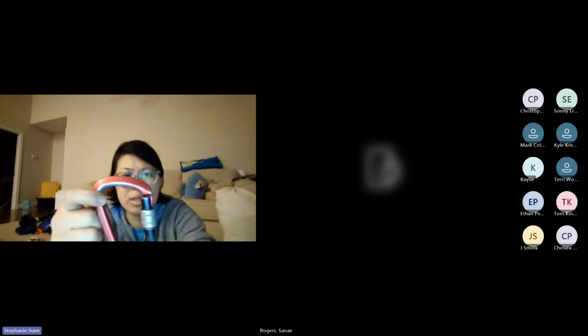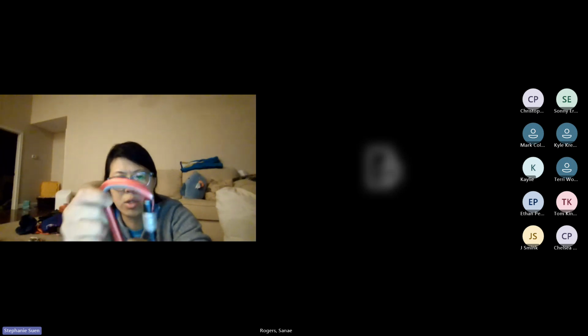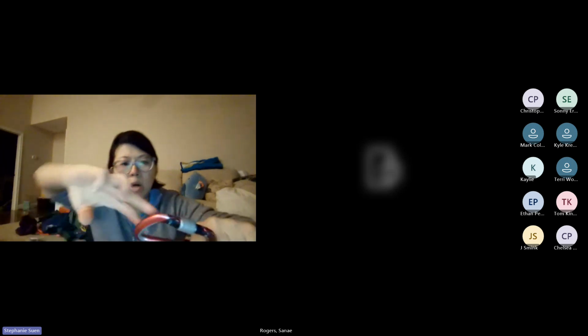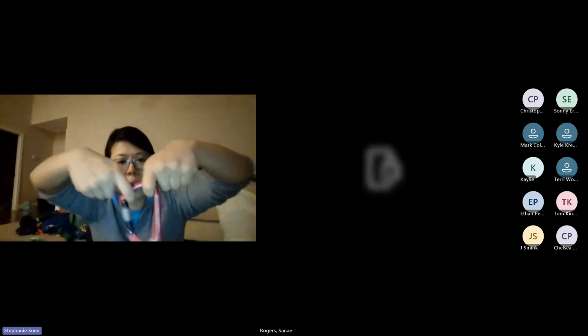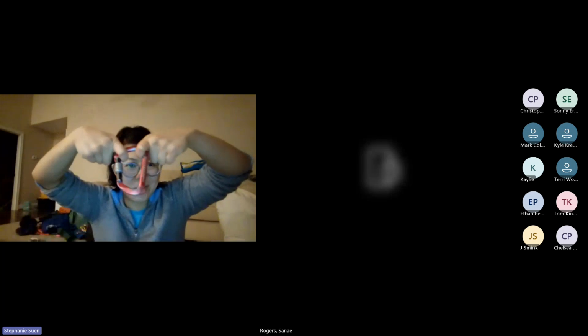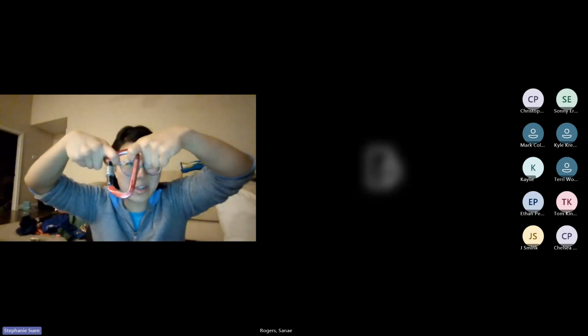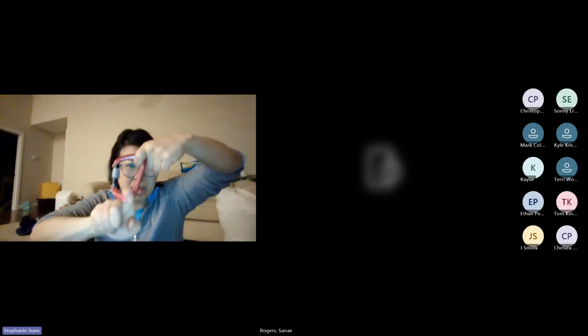One of the things that we don't necessarily want to do is tri-load a carabiner. What that would look like is, you've got the anchor points. Say you had a piece of webbing and you did a basket hitch, and the two ends of the basket hitch are pulling on this and your rope is coming off of this. That's called tri-loading, and carabiners super don't like to be loaded in three directions like that, right?